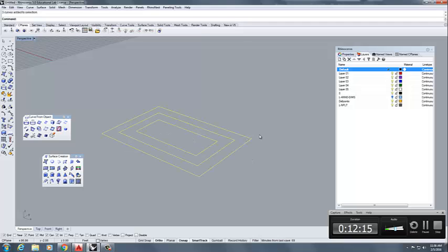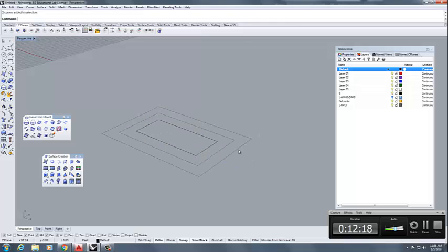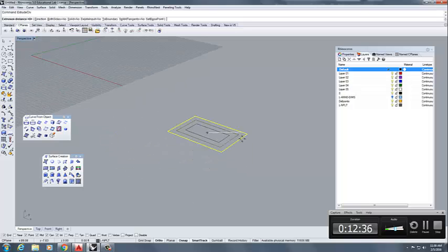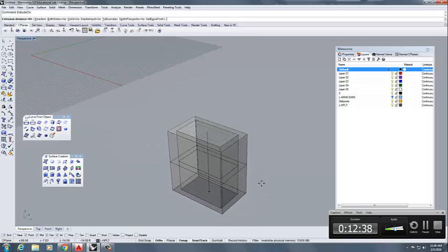Okay, I'm running out of time here. We do these lots of different ways. These walls, because these are at the right elevation, they were up at the dam wall height, I'm just going to extrude those down any random amount. I'm going to select both of them and type extrude curve. As it comes up, it's extrude CRV. Hit spacebar and extrude them down. I can go to any distance I want.